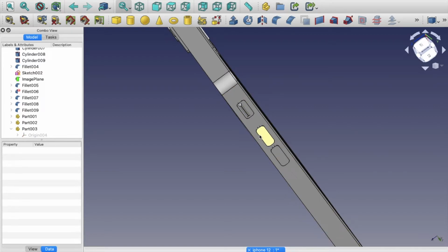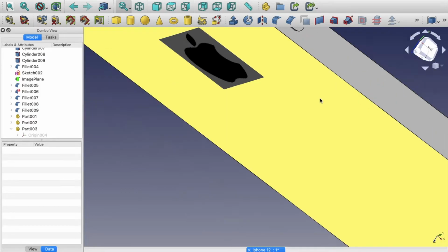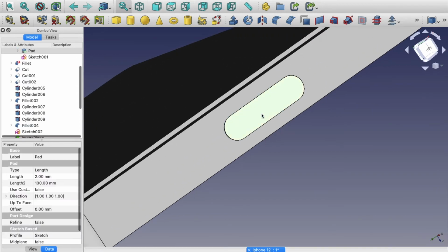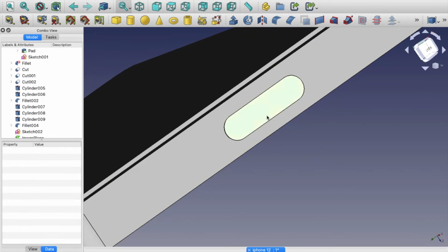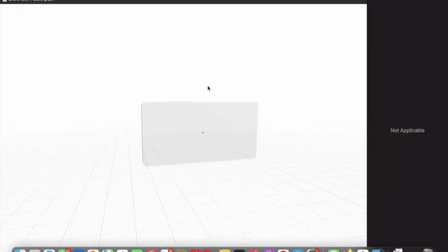After making the rocker button, I come to the silent ringer switch, in which I use the cuboid option and two cuboids which are smaller in dimension. After that I come to the charger part, I use the same thing, and by using the boolean operation, I cut it out. After completing the project, I convert it into an STL file.